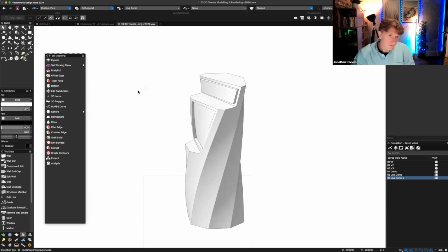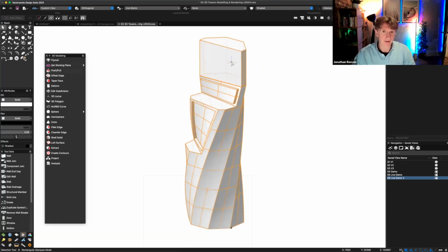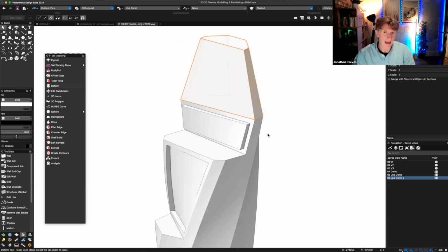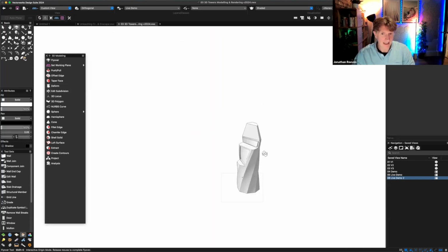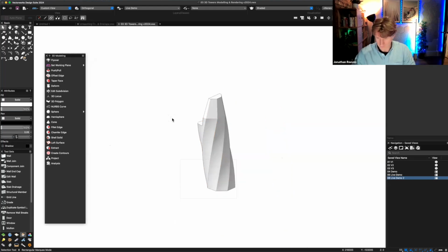As well as that, the deform tool has a very nice taper mode. Okay, so let me just do something with the push-pull tool. What I'm going to do is push and pull another edge here and just ungroup that one so this one is separate. That means that I can use the deform mode to see if I can taper it in a little bit there, just on the top. Can you see? So very easy to taper. And then when I'm ready, if I want to, I can select both of those and just add them back as a solid again. So that's pretty cool.